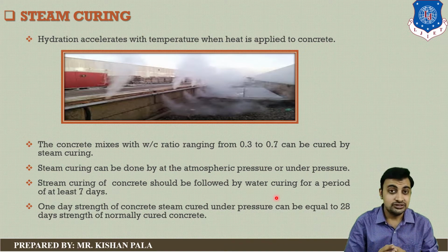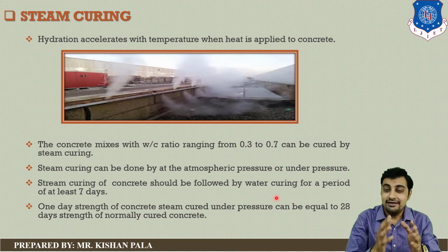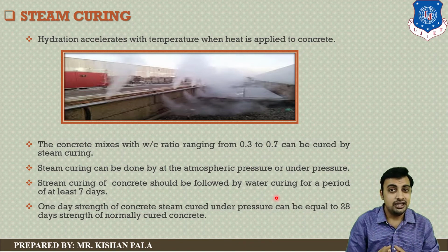So depending upon the situation, the type of concrete and the requirement of the concrete mass, you have to choose any one method and apply the curing to the concrete mass to achieve the hardened property as well as the durability of the concrete mass.